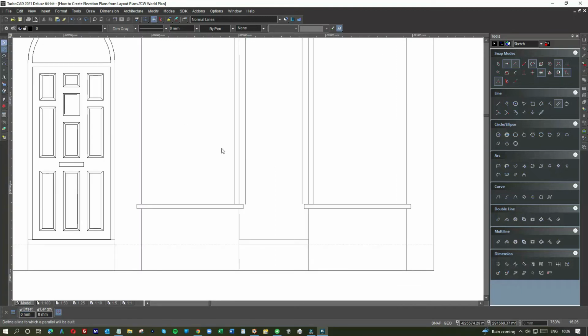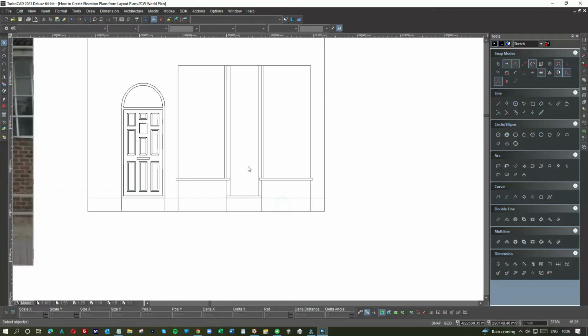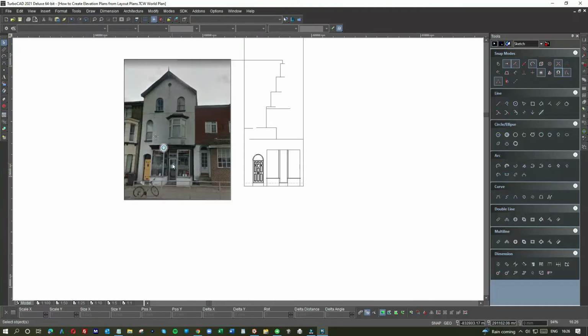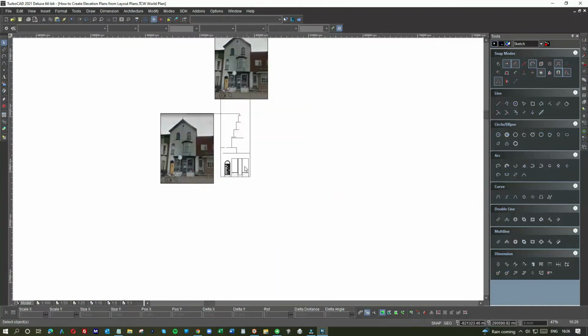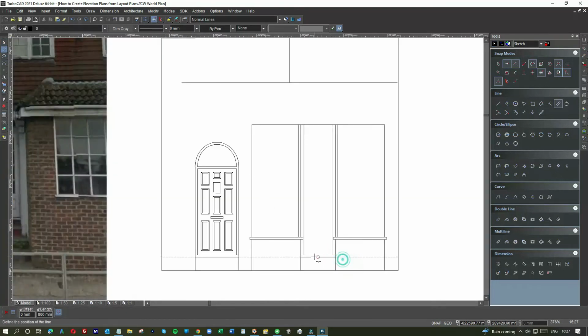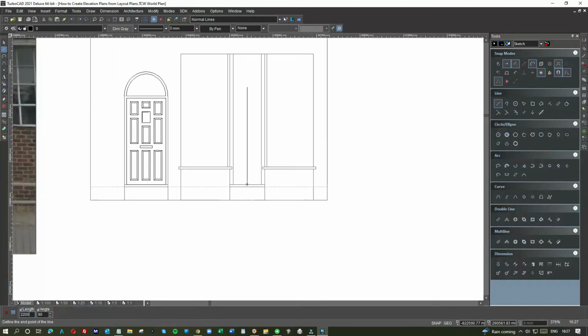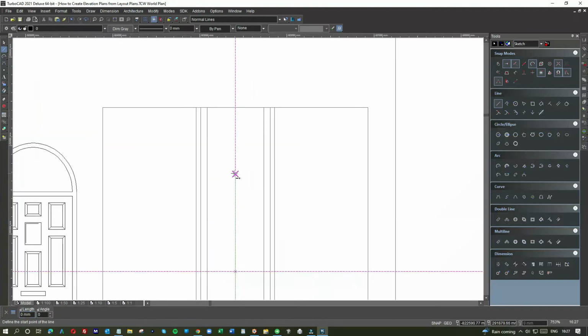So now what we do is come on down, and now we're getting access to the door. So if I look and I say it's extra tall, I say the door is about 2.2. Let's see what 2.2 looks like. I'm still in the wrong tool here. Tab 2200. Yeah, that looks about right. So this is the actual door.